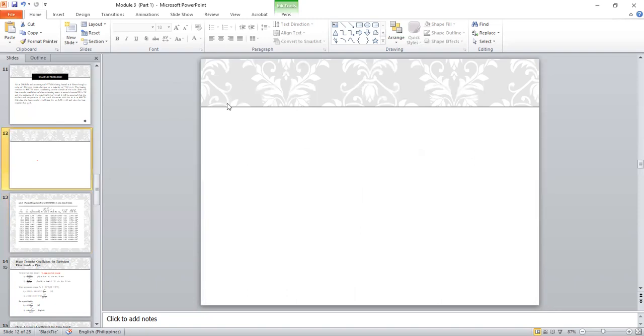So as a continuation, we substitute into the Reynolds number. Our inner diameter is in mm. If we want to have everything in SI, we need to convert it to meters. So converting it to meters would make it 0.0254, because it's 25.4 mm. So 0.0254 meters, and this is for the D.